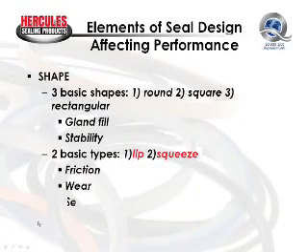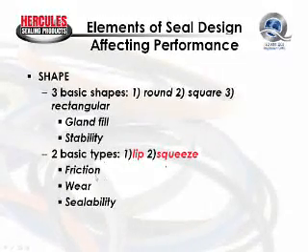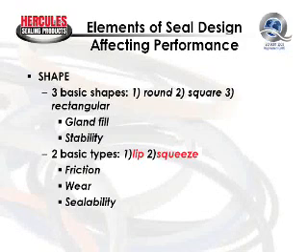So, with our lip seals or squeeze seals, we're concerned about friction, concerned about wear because of increased friction, and then ultimately we're concerned about low pressure sealability. Because we've already mentioned that most of our sealing problems occur at low pressure. At high pressure, shape has very little to do with sealability. Shape is only important at low pressure.